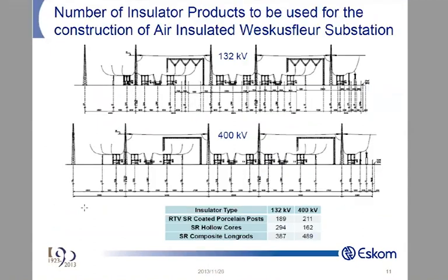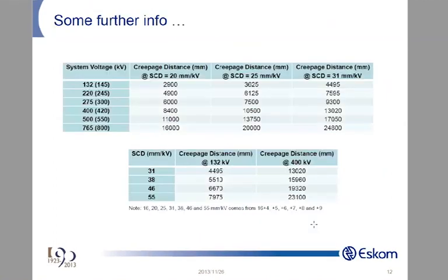Tool is working. Now we take a look at the substations we want to build. We want a 400 kV sub, a 132 kV sub, with breaker-and-a-half designs and all those issues. And now how many insulators are we going to have there? Because remember, statistically, with 1 insulator your risk of flashover is far lower than with 100 insulators. So now we need to find out how many insulators we have so we can calculate our risk. Cool, there we go. We're going to need so many coated ones, so many alcohol ones, and so many silicone ones for the 132 one that we do.